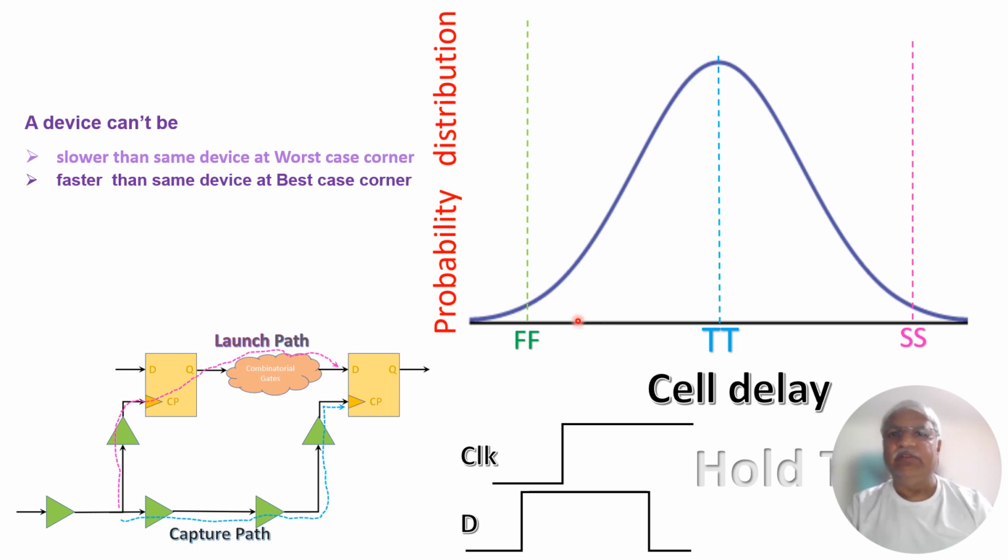To mimic this local variation scenario during simulations, we will take a derate factor of 10% here and apply it to the clock path, because now we are thinking that this is coming at the fast corner, with NMOS and PMOS both in fast condition.